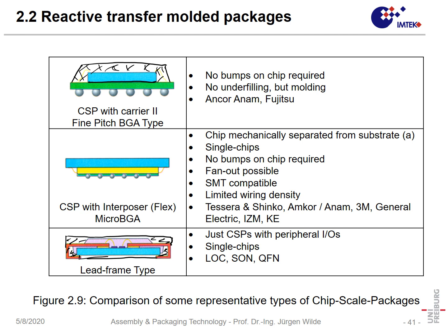Then put that whole device into the molding machine, and either selectively or generally mold it. So that is a chip scale package, but it uses normal lead frame and molding technology.